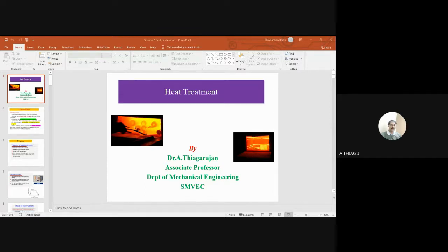Then the sample is allowed to cool. Then all the austenite, can you see the phase? All the austenite is changed or transformed to pearlite. Pearlite is a formation or mixture of ferrite and cementite. So what will this material be? This material, ferrite, is more soft in nature.